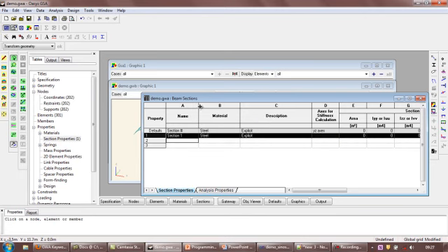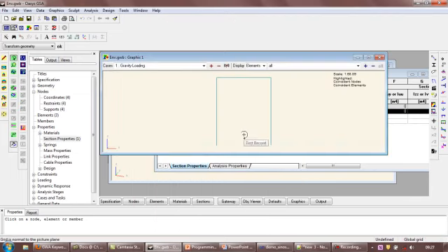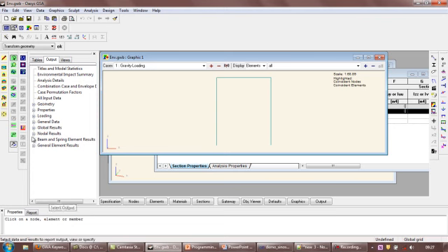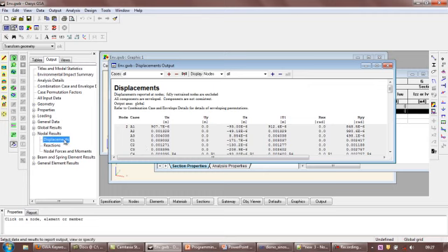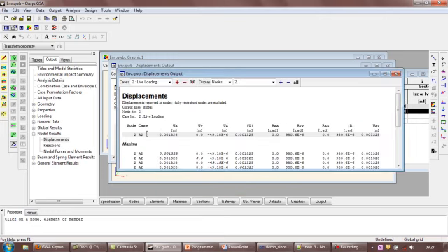If I look at a model that's analyzed, and I want to look at the nodal displacements, if I select node 2 and analysis case A2, it gives me all the available results for this node for this particular load case, and I can look at the X translation, Y translation, and so on.